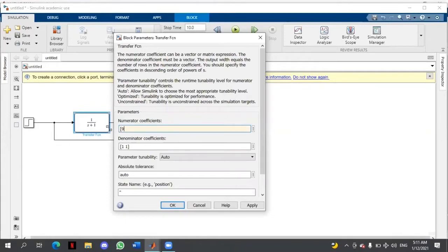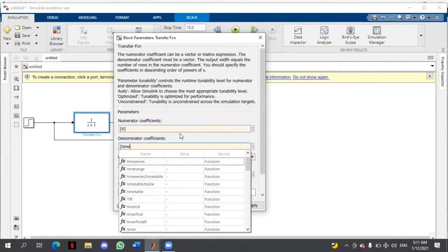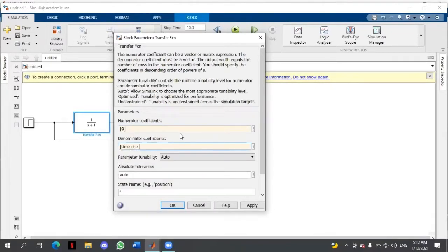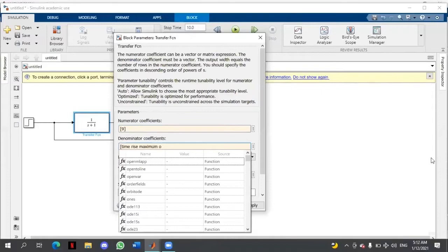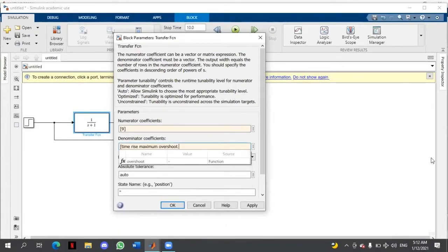Each signal can be either a scalar signal or a vector signal. For single input systems, scalar signals are generally used. For modifying a block, a block can be modified by double clicking on it. This dialog box contains fields for the numerator and the denominator of the block's transfer function. By entering a vector containing the coefficients of the desired numerator or denominator polynomial, any desired transfer function can be entered.